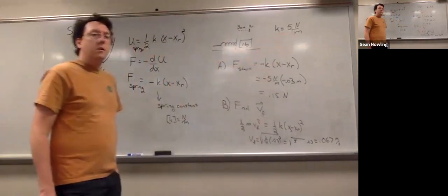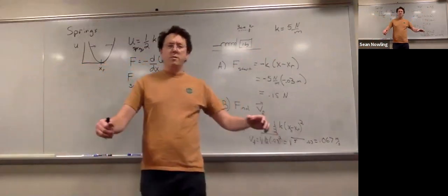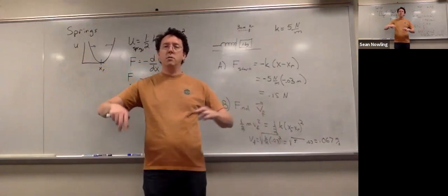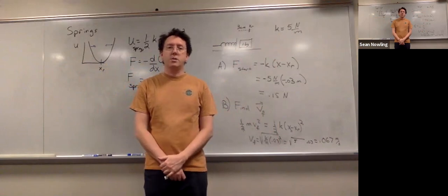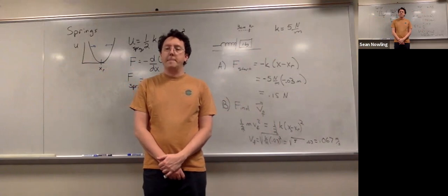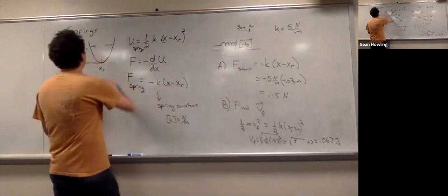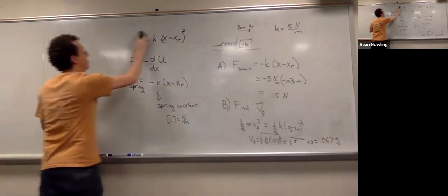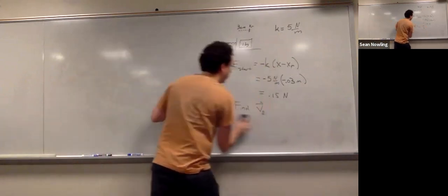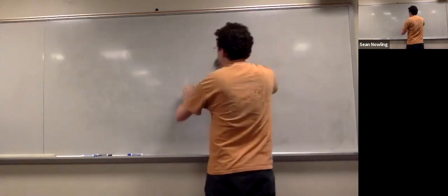Okay. Other examples like this could be things like, I think there's a sapling question where you've got a car, so you have to distribute the force between all of the different shocks. Each shock only carries 1/4 of the weight of the car. There's a nice formula when you have springs that are in parallel versus series, for combining them to get an effective spring constant. I'll leave it to you. You can read about it in the book.